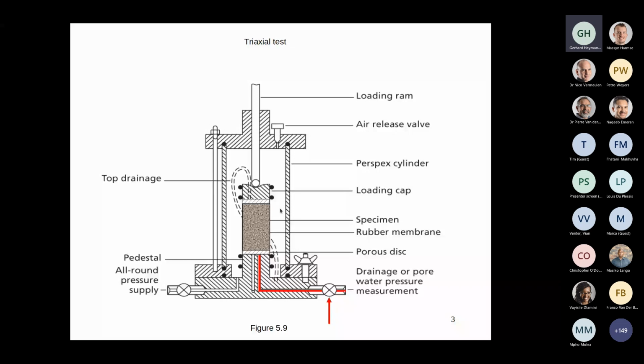busy with the consolidation stage. Okay, now we're going to say quite a bit about this valve, which we call the drainage valve. And this valve is the valve by which we can, if we close this valve and this fully saturated specimen, no water can enter or leave the specimen. Now, interestingly, we have the choice of either leaving this valve open or closing it during the consolidation stage.